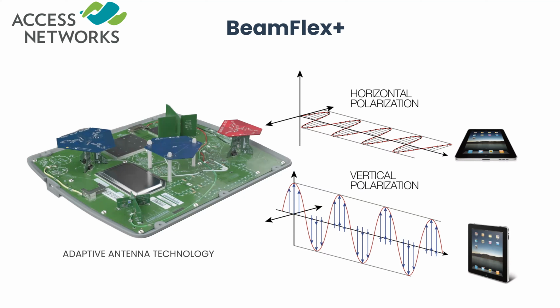Well, if you laid the laptop down, you'd be out of polarity with that wave, so you'd have very little of the energy actually making it to the antenna. Well, when your mobile device goes through the environment, it's always going in and out of orientation with that polarized transmission. So literally the Access Networks access points have antennas, some that are transmitting horizontal, some that are transmitting vertical.